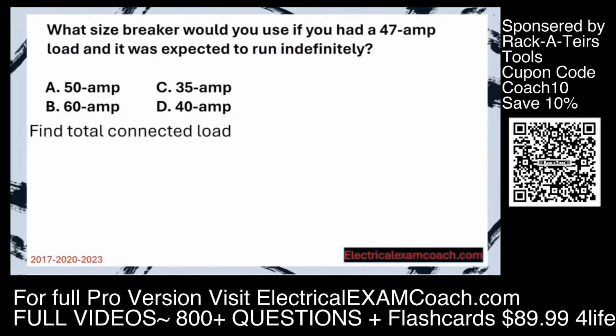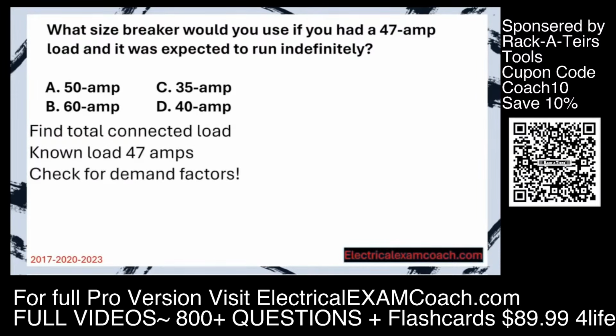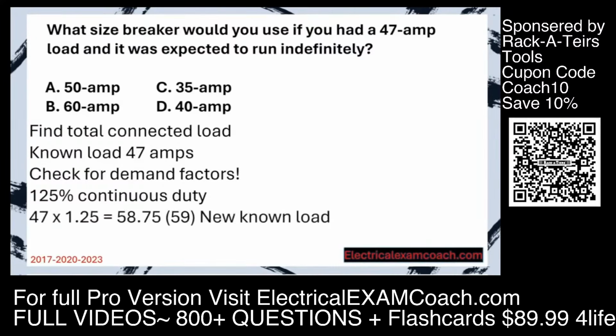Step 1, find the total connected load. Our starting known load is 47 amps. Now we check for demand factors. And in this case, it gets that 125% continuous duty, just like a continuous load. We take our starting known load, multiplied by 1.25, and that equals 58.75. And in this case, we would round up. So 59 is our new known load.